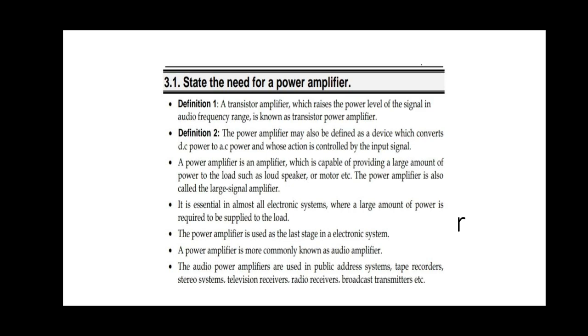It increases circuit stability. The output of an ordinary amplifier is easily changed due to variation in temperature, frequency and signal amplitude. This changes the gain of the amplifier, resulting in distortion. However, by applying negative voltage feedback, the voltage gain of the amplifier is stabilized, accurately fixed in value.